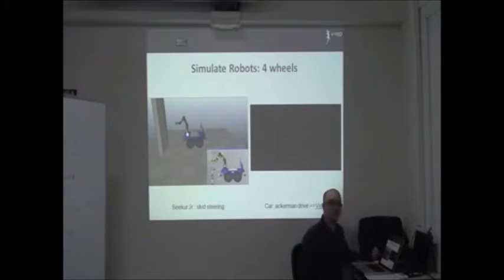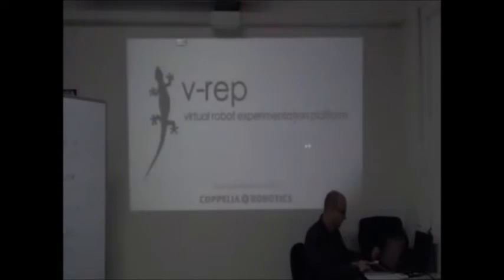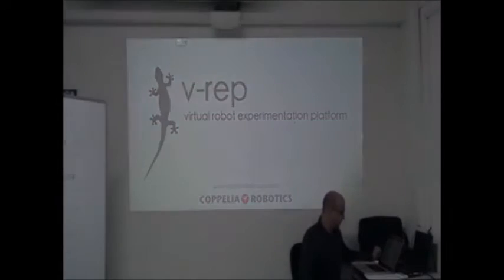Four-wheel robots are very good for rough terrain, especially with this configuration. This is not a steering model. This is four fixed wheels, and by making some combination of wheel rotations, you are able to model this robot like a skid steering robot, which is modeled like the differential drive robot Andres presented.